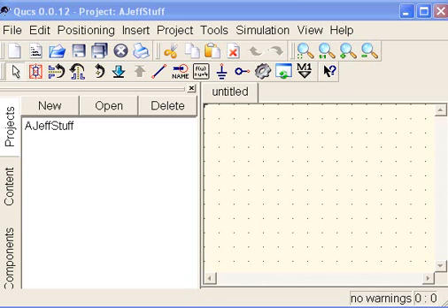Okay, here's a tutorial startup for Qucs, which is Quite Universal Circuit Simulator. This is an open source harmonic balance simulator that supports DC, transient, AC analysis, harmonic balance, S parameter simulation, and it's something that I couldn't find a whole lot of tutorial help on on the web, so I got familiar with it enough that I decided to post